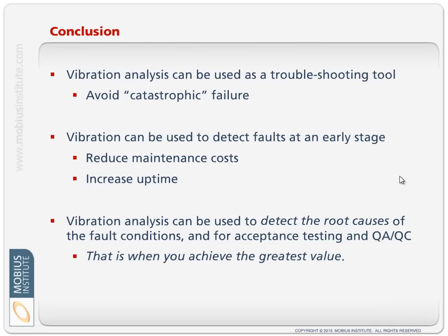And my last comment, I made the comment at the very beginning, but I'd just like to repeat it. Some people use vibration analysis almost like a troubleshooting tool. We're taking measurements just like old Joe used to with his screwdriver, and just like an operator might hear that the machine has a problem. We are hearing and detecting problems that shouldn't exist, and we are often just looking for the bearing faults, the thing that we think, oh well, that's what's going to cause the machine to fail, so let's focus our attention on detecting bearing faults.